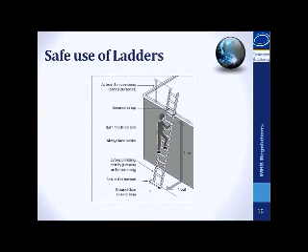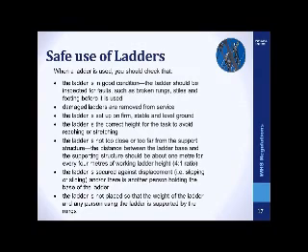The following diagram indicates the safe use of ladders. The safe use of ladders. When a ladder is used, you should check that the ladder is in good condition. The ladder should be inspected for faults such as broken rungs, stiles, and footing before it's used. Damaged ladders are removed from service.